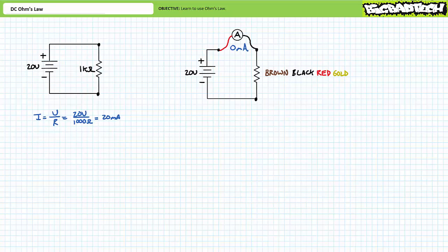I previously assured you that it was in fact a 1 kilo-ohm resistor. However, are it and the ammeter the only elements in the circuit with this source, or is there something else in series with it? Think about what I'm asking. What is something with an infinite resistance? Something with an infinite resistance is an open or an incomplete circuit. This is where intimate knowledge of your circuit building environment, typically a protoboard in lab, comes into play. You may have the correct voltage and you may have the correct resistor, but a complete circuit may not exist because of an inadvertent open.